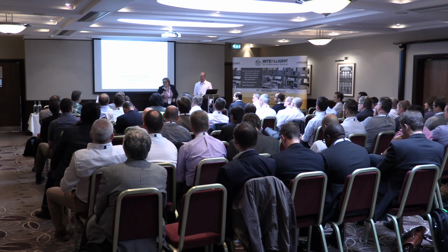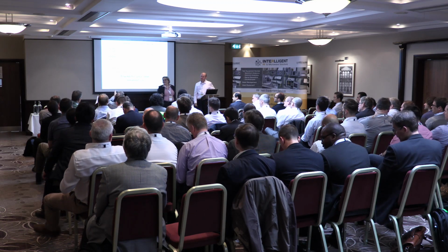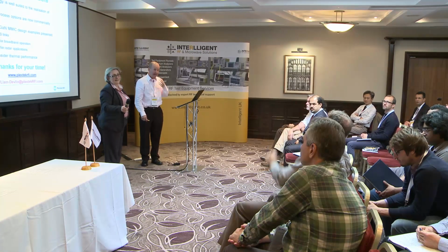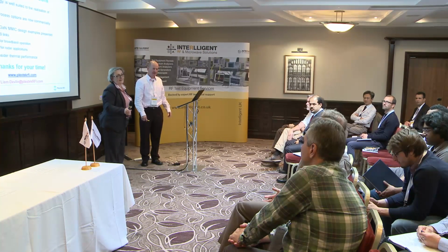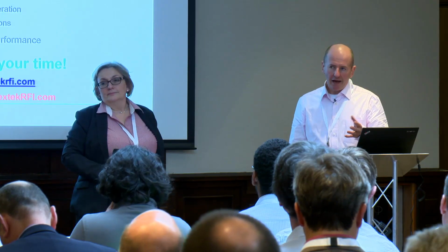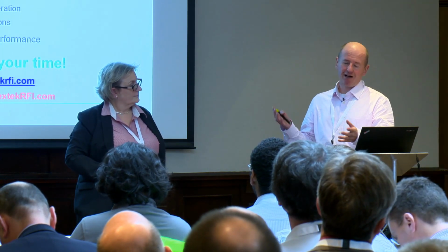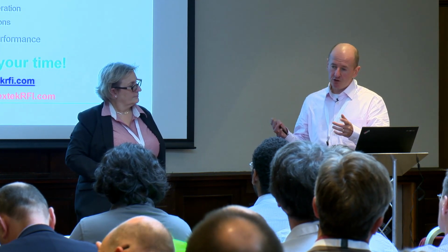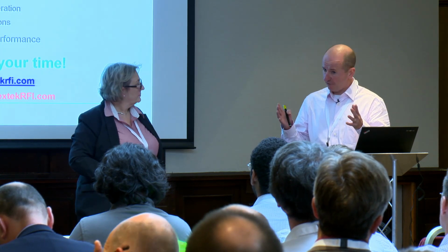Yes. The comparison of size where you showed the GaN device and the GaAs device. What's the cost delta between the two? Account for the size difference. It varies all the time, and it depends which process you use, but it's roughly 2 to 1. For a foundry that has both, it's round about the 2 to 1. Per unit area, very roughly.